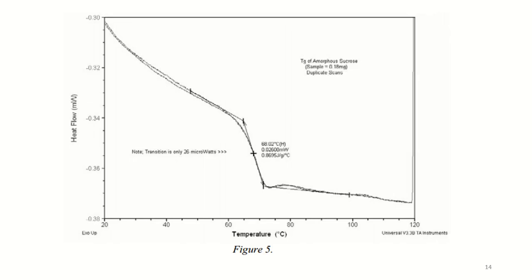At the expected glass transition temperature, a very small step change of 8 micrograms is detected. Comparing this change with that of a 100% amorphous sample permits the calculation of the amount of the amorphous structure in the crystalline sample.